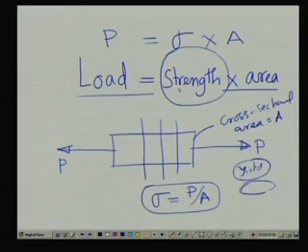So the stress generated will have a maximum limit, and we consider this to be the yield strength. The yield strength of the material multiplied by the area is the maximum amount of load. In other words, the stress generated can go maximum up to the yield strength value of this material.